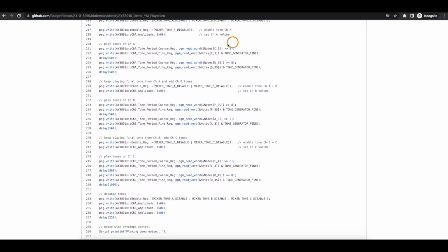Then, using those shortcut note references, I'm playing a C note from their arbitrary third octave frequency. Since this is, I believe, a 12-bit data configuration in these two registers, we have to send the data out in two commands to get to the two different registers, coarse and fine. So I'm playing this C note for half a second.